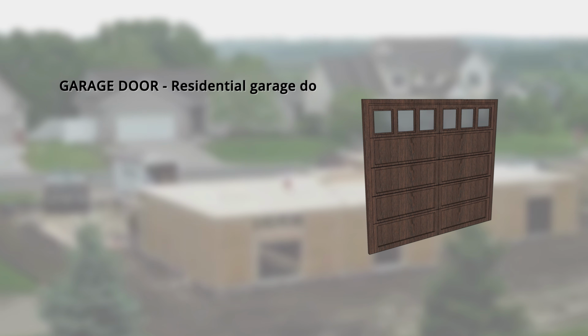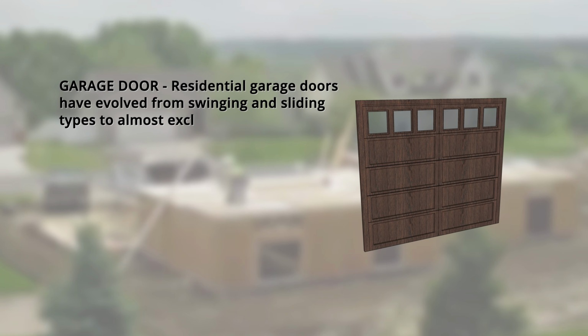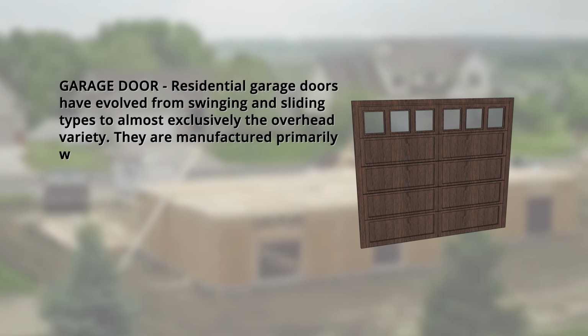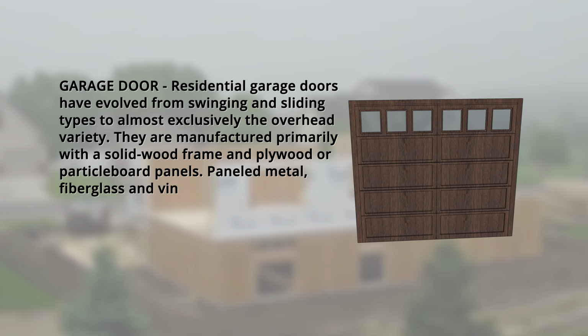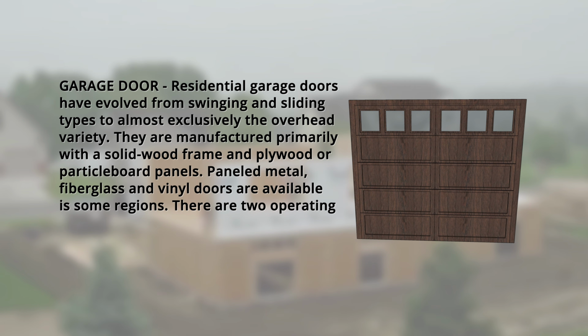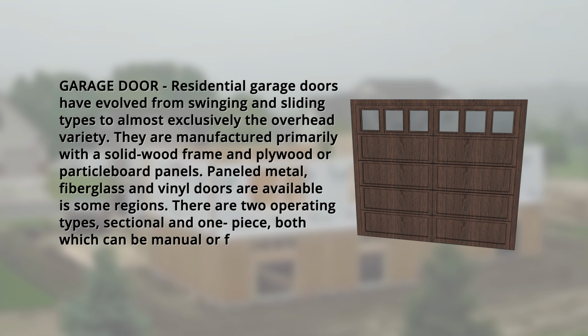Doors. Garage door. Residential garage doors have evolved from swinging and sliding types to almost exclusively the overhead variety. They are manufactured primarily with a solid wood frame and plywood or particle board panels. Paneled metal, fiberglass, and vinyl doors are available in some regions. There are 2 operating types, sectional and one-piece, both of which can be manual or fitted with automatic openers. Take a look at this detailed illustration.